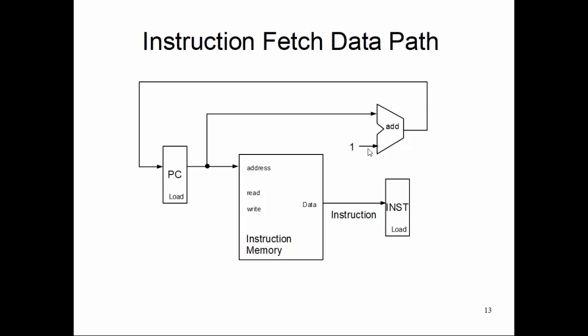But for our class, our assumption is our memory is word addressable, so that's why we will bump up PC by 1 address. So from the startup address, you will have one more to point to the next instruction. So we deploy an addition circuit there. My current PC plus 1 is going back to the PC register. So these are the components, right?